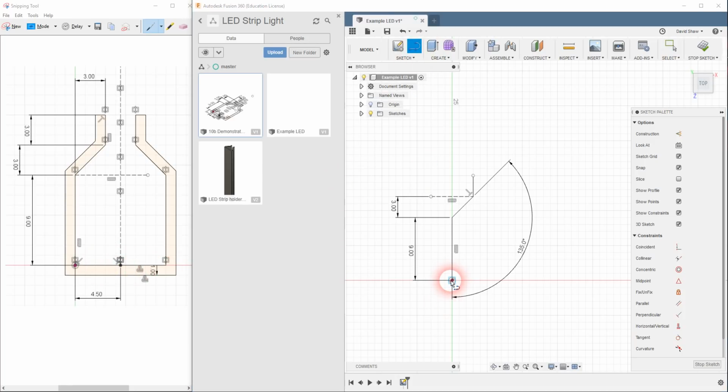Let's make a line tool again here. Let's take it in here, 4.5 millimeters. Now that's off the grid. So what I'll do is I'll dial in 5 for the time being. Notice I can also go to the tick box there, or I can also press the escape key on the keyboard to finalize that. Let's get the D tool for dimension. Let's bring a dimension line in here, and let's put that to 4.5. Okay, so that's basically got my basic shape in place. Let's now do a mirror of this. I've got the dimension line tool, so I'll press escape to get rid of that.